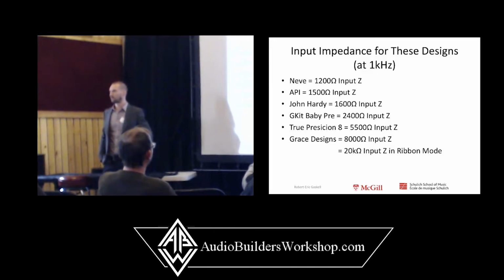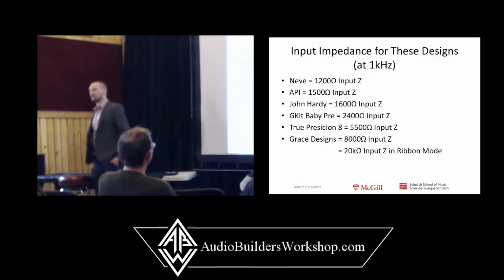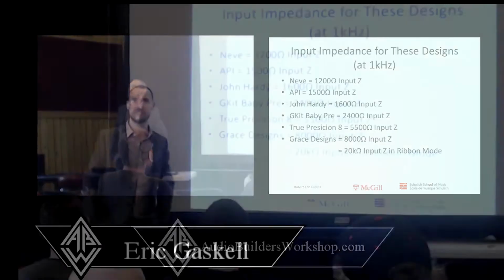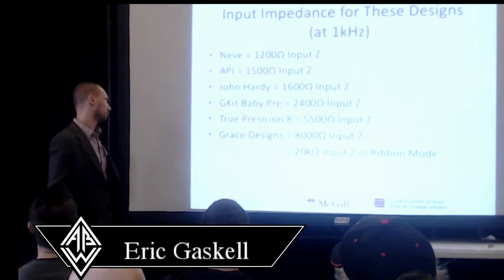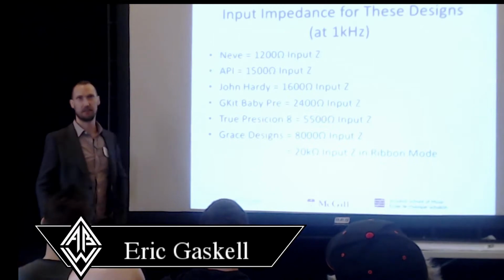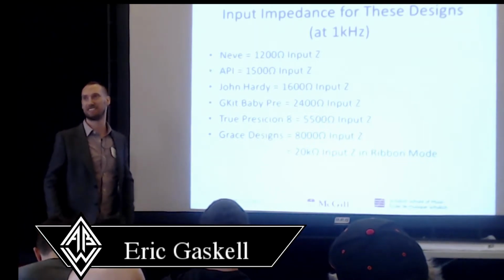So I have a gap pre, a 500 series pre, and it has a switchable input impedance. And the values are 300, 600, and 1200. In most modern mic preamps, is the input impedance as high as these values? Because 600 seems like a baseline, but 300 seems pretty low. It really was pretty damn low compared to this. I could see 600 because of the power matching philosophy of the olden days.